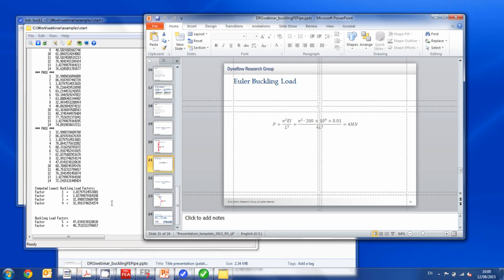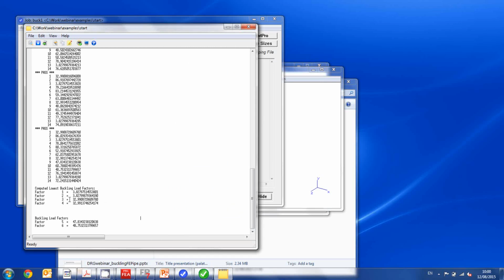If we then go back to this buckling report, we see for the second order buckling mode, the 3/4 sine wave, there's a margin of 32. So there's no chance of exciting that, it would always fail with the first buckling mode. And then if we go to 5 and 6, this was the shell buckling mode, we see there's a very, very large margin.